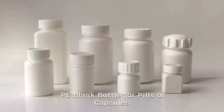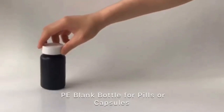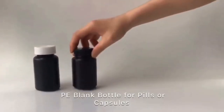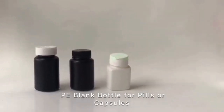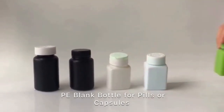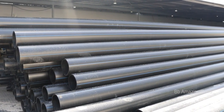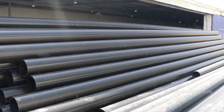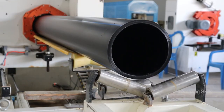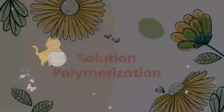And the HDPE containers and bottles, the application is packaging for chemicals, detergent, oils, and other liquids. HDPE's chemical resistance and durability make it an ideal material for containers that need to withstand a variety of contents. The last one is HDPE pipes. The application is municipal water supply, gas distribution, industrial pipelines. The reason is HDPE pipes are known for their strength, durability, and resistance to corrosion, making them suitable for transporting liquids and gases.